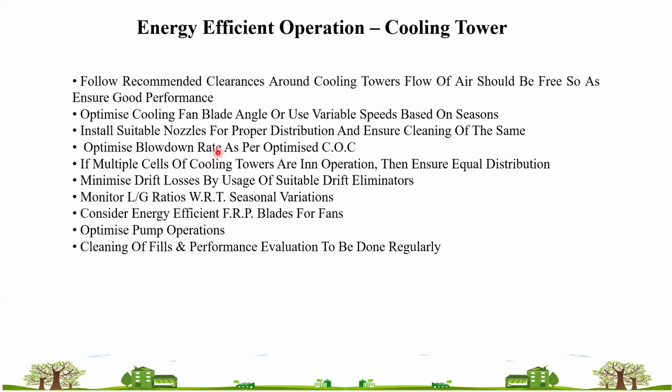Your cooling tower liquid ratio is on the higher side, so you are not adding any value to the system. Your pump operation has to be optimized. Then cleaning of fills and performance evaluation have to be done regularly.